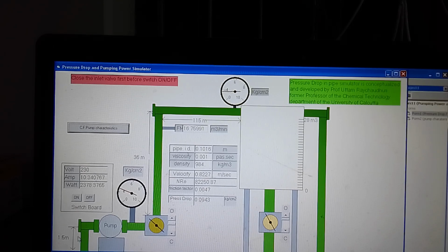I think I have explained the necessary requirements for running a centrifugal pump. Let us close the valve before stopping the pump, otherwise the motor will be damaged or shocked. So we will switch off the pump. This valve is open, so you can close it in order to see the flow rate. As and when you switch it on and gradually increase it, you will see that the flow rate increases, which is shown as the level rising as flow increases.